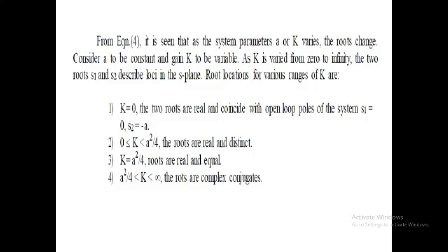We should note that the breakaway and break-in points must be roots, but not all roots are breakaway or break-in points. If a root is not on the root locus portion of the real axis, then this root does not correspond to a breakaway or break-in point. If the roots are a complex conjugate pair, ascertain that they lie on the root loci and check the corresponding value of k. If k is positive, then the root is a breakaway or break-in point.